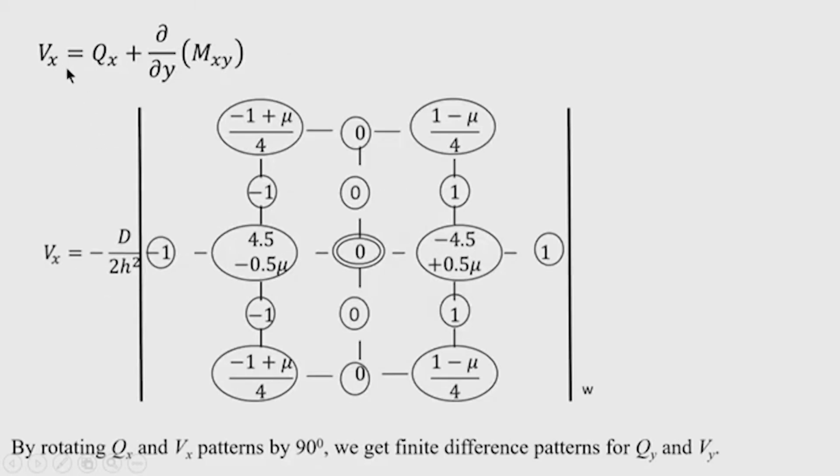So, the S shear force, that is, we need to apply this condition specially at the edges, for such edges where the force boundary condition has to be imposed. For example, for a free edge we know that the shearing force is 0, the twisting moment is 0, as well as the bending moment is 0.